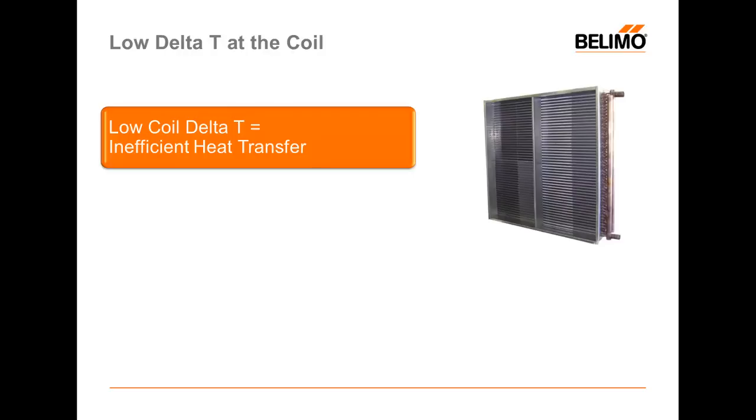When you send very cold water down to your chilled water coil, if you do not transfer enough heat, that water will remain cold and get sent back to your chiller at a colder temperature than is designed. This is what's known as a low Delta T. It's inefficient for several reasons.